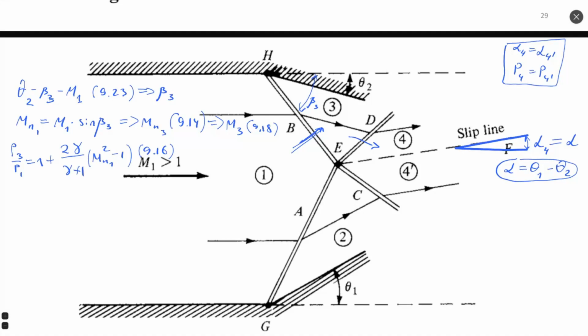Okay, and then we will have the transition from region 3 to region 4. How do we obtain this transition? First of all, we need to know the angle of the body. In our case, the angle of the body, theta, we will call theta 4. I will continue this line here of the vector from volume 3, and this is theta 4 between flow direction in region 3 and region 4. And this theta 4 will also be related to our alpha direction.